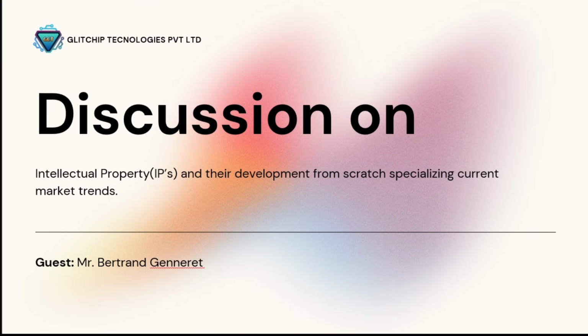Once you have it, you move towards architecture design. Architecture design is to develop the high-level architecture of the IP. At this step, you will define an overall picture of your IP with the different blocks and how they interact together. To be clear, it means that you will decide the major components and how they interact, and you will clarify the data flow within the IP. So this is about architecture.